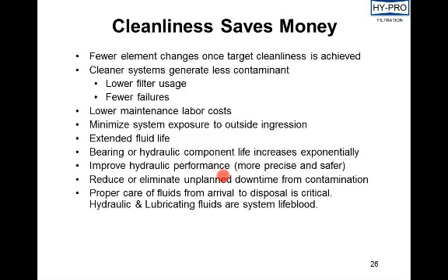But the biggest difference we find is a filter element rated for DFE does not unload nearly as much contaminant as one that isn't, especially on the restart test. It can be a factor of 10, even up to as high as a factor of 20, where ISO standard validated filter elements unload a lot more contaminant than those rated to DFE.